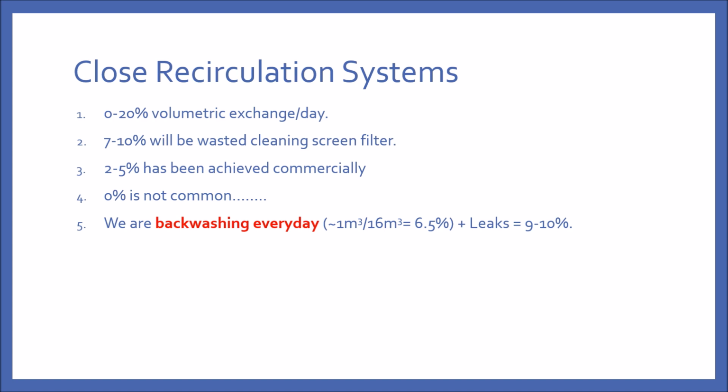It is not that we intentionally change out the water, but instead you sometimes lose water from the backwashing of the filters. So it is by operating the filters that you do lose water, irrespective of the filtration media that you will be using.